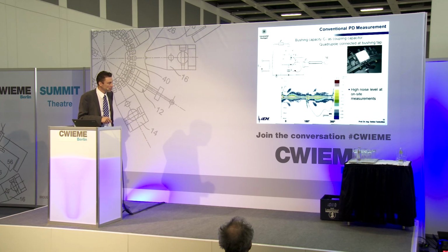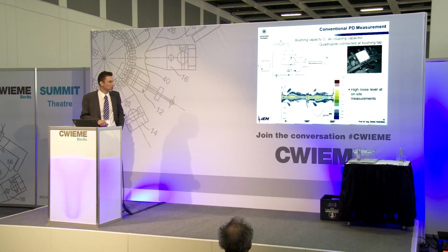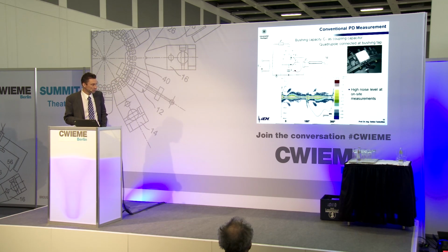So you have here on the x-axis the phase angle of the applied voltage. So here 0 degrees, here 360 degrees. You can see here the applied voltage. And in the case of these offline measurements, you do not have a perfectly clear 50 Hertz. You also have resonances on this voltage, which result here in this buckling of the sinusoidal curve.